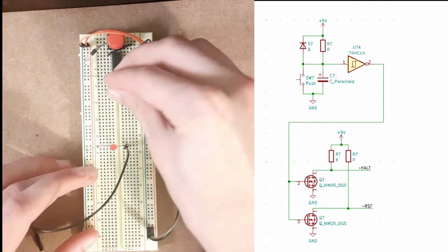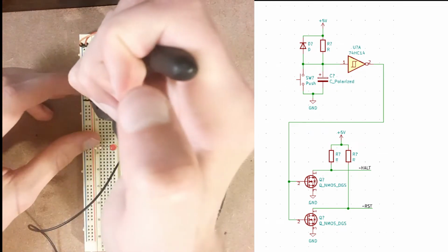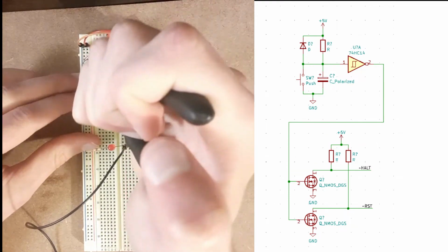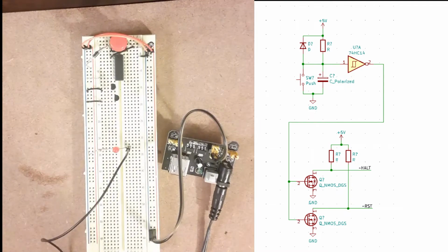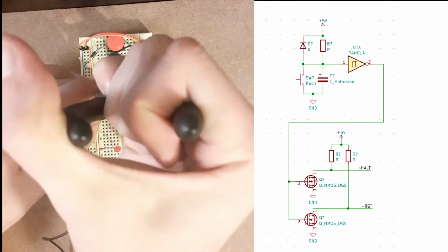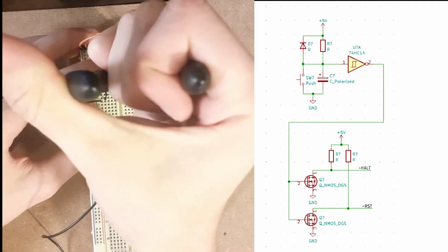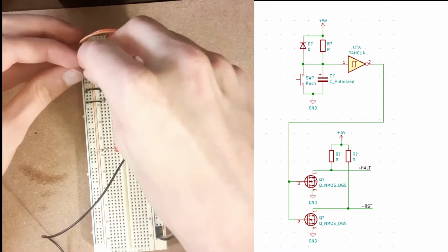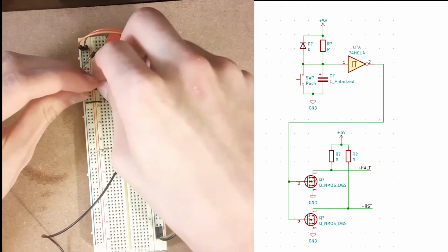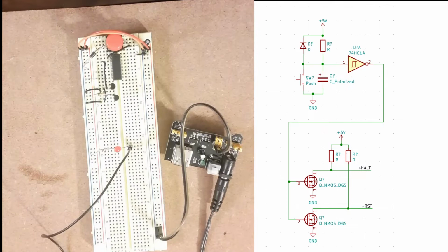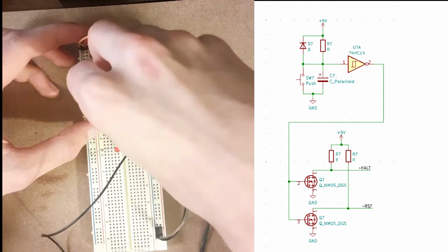Now, to reset the CPU, we need a low pulse on both the halt and reset pins. However, both of these pins are bidirectional with open collector drivers. This means that the CPU can drive the reset and halt pins low by itself, which happens when the CPU executes a reset instruction, which allows the CPU to reset external peripheral devices. So wiring the reset circuit to the reset and halt pins directly would create a short circuit if the CPU executes the reset instruction.